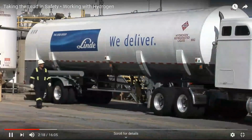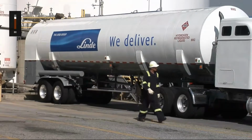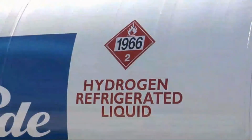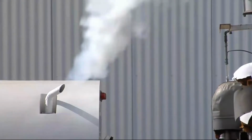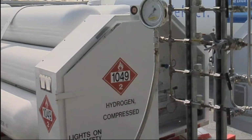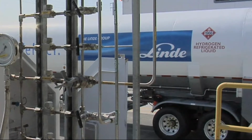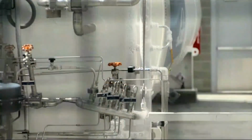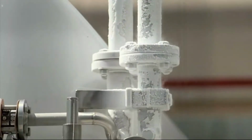Hydrogen can be converted to a liquid if it's pressurized and subjected to extremely cold temperatures, which is how it's normally stored and transported. It's much more economical to transport and store hydrogen as a liquid because the liquid expands into a gas at a ratio of 850 to 1. That means you need 850 tankers of hydrogen gas to deliver the same amount of material as one tanker of liquid hydrogen. Liquefied hydrogen is one of the coldest materials used in any industrial setting. It's normally at 423 degrees below zero Fahrenheit. The only colder liquefied gas is helium.